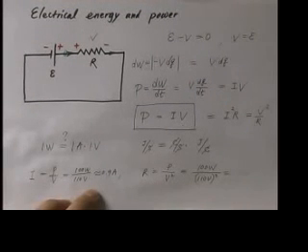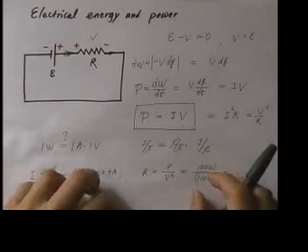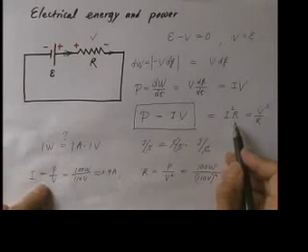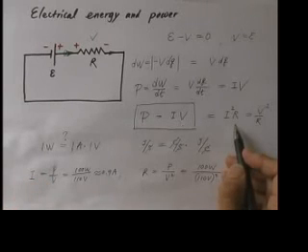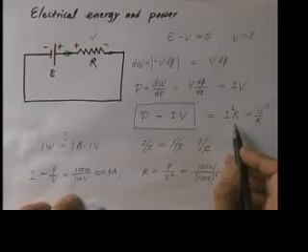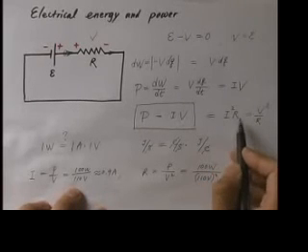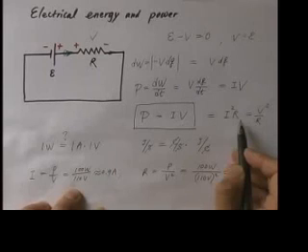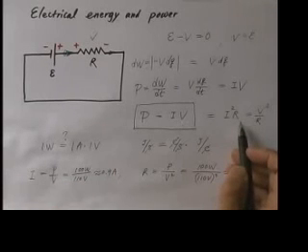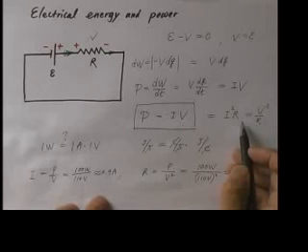Another thing that will come back later, and I just want to start mentioning here, is that the electrical power dissipated into thermal form as a current I goes through a resistor R goes like I squared times R. Now, this issue becomes important when it comes to transmitting electrical power through power grids. Power plants are usually built in a rural area, and the heaviest consumption of power is usually concentrated in a big city, and there could be many miles of transmission lines between the power plant and the load, which is in the city.